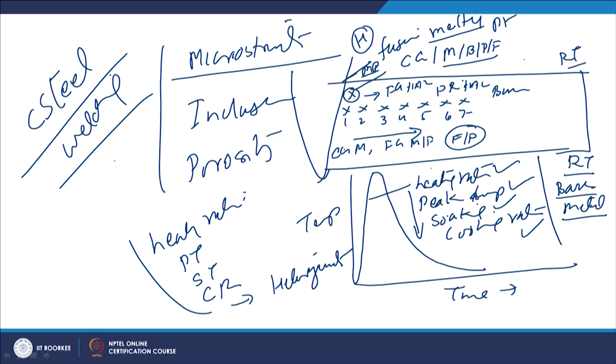until the base metal. But the weld metal experiences the highest cooling rate. So, there will be every tendency for the formation of martensite, and that too of fine grain structure, if autogenous welding has been performed. But we may regulate the weld metal composition as well as properties using a suitable filler or electrode that will help in having a suitable combination of properties in the weld metal. So, we can do a lot for regulating or adjusting the properties of the weld metal, but we have limited things to do for changing the properties of the heat affected zone, and that is why, especially in case of steels, control over the properties of the heat affected zone to a great extent determines the ease of welding.